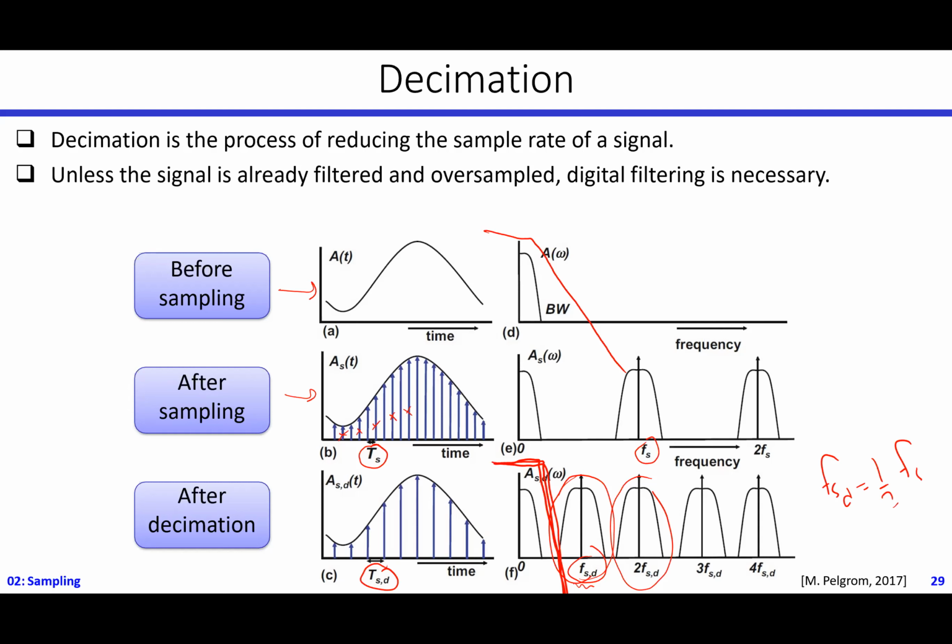So actually what we are doing is reducing the cost as well as the power of the sampling and the use of the filter, right? Yeah, basically we made our life easy, but I don't want to continue with all the digital parts at this very high frequency. I don't need that high a frequency for my application. I can reduce it before I do all the other processing, and that's why it's a sub-sampling process. Sorry, a decimation process is again like sampling at a lower frequency than what we originally have.